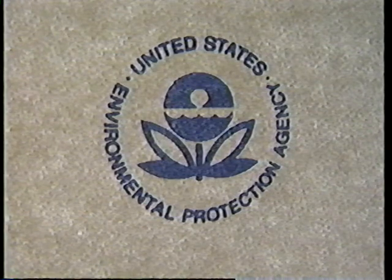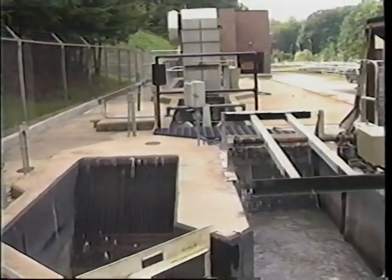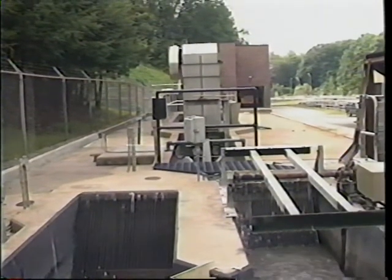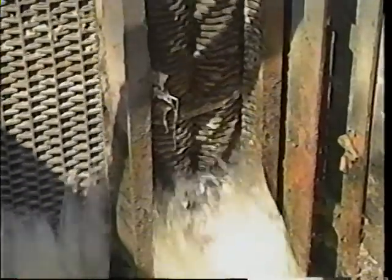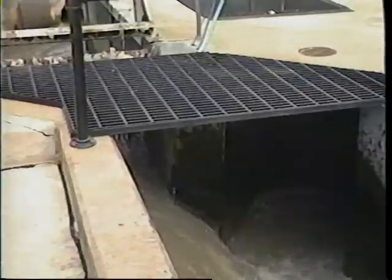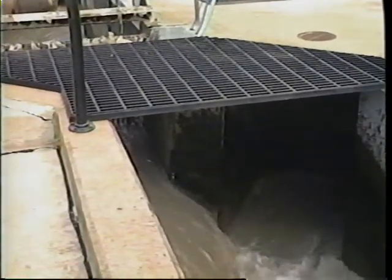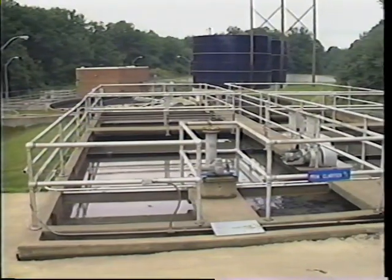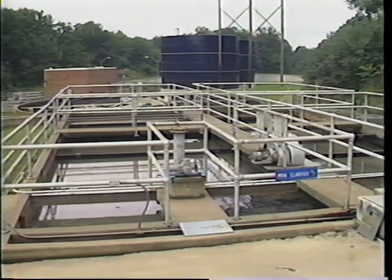Not all treatment plants are alike, but they do share similar flow patterns in accomplishing common goals. Upon entering the treatment plant, wastewater usually receives preliminary treatment that may consist of screening, shredding, and grit removal in order to initially remove coarse material. From there, the wastewater usually goes through a flow measuring device in order to record the influent flow rates and volumes before entering the primary treatment stage where solids will be separated and removed.